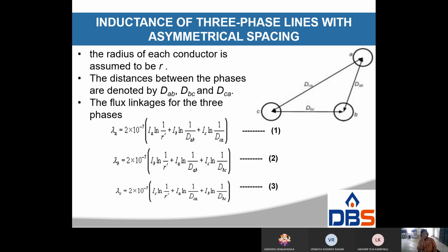Two marks important: what is transposition of a transmission line? Changing the position of each conductor so that each occupies the original position of every other conductor. This exchange of position of conductors is called transposition of conductors, right?